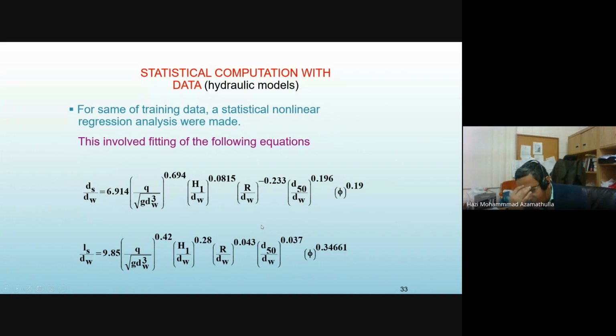You can also see the very important bed material size in the model. That is our drawback: we consider 2 mm, 3 mm sand. I use sand; I cannot put big boulders, right? Also the lip angle of the bucket is very very important. You can see 0.9. So you proved, right?